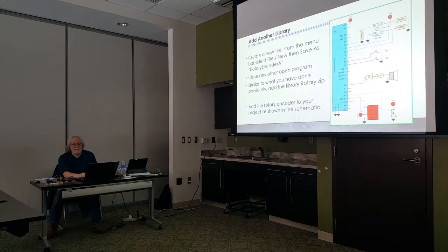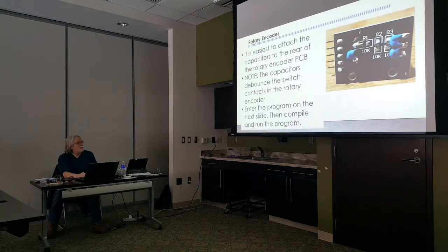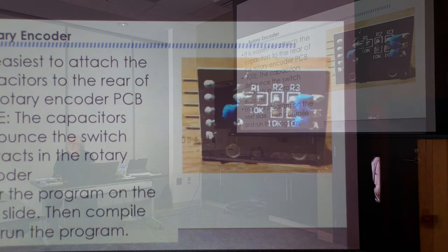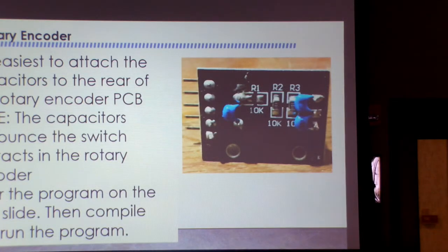It's the same process. Debouncing. The push buttons and the rotary encoder, you need to debounce the switches in software. And it's not hard, just time consuming to write the code and test it. Or you can put a big cap on there and hope that between the cap and the pull-up resistor, you've got a nice RC time constant that filters out switch bounces. And switches do bounce. When I pushed the button down, it did not close just once. And when I let it up, it did not open just once.